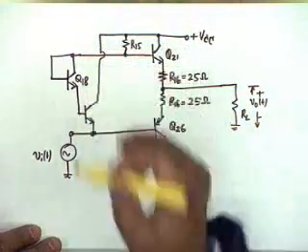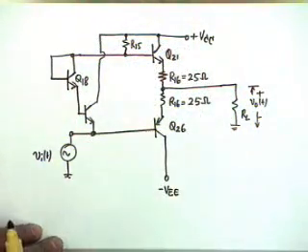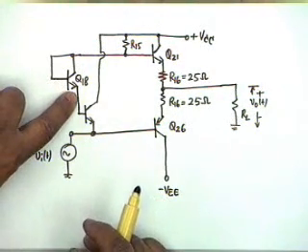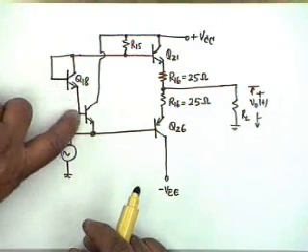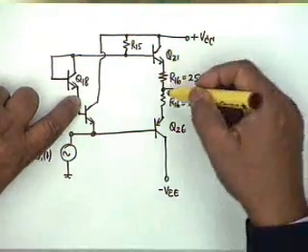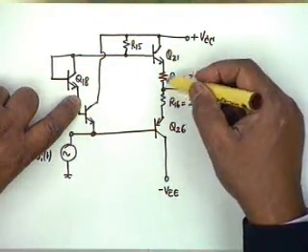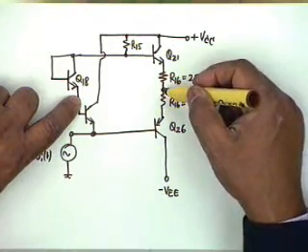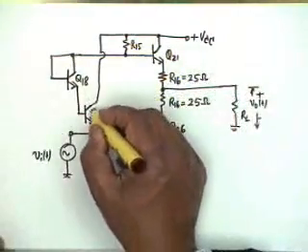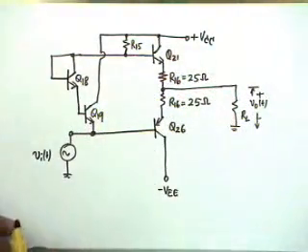Does this make a difference? As far as the balancing is concerned, this base to emitter shall be 0.7 and this base to emitter shall also be 0.7. All that we needed was that this junction should be the same potential as this junction, and from symmetry there is no reason why these two voltages should not be equal. Q18 and this is Q19 are identical transistors, and therefore the voltages at the base, VBE, should be identical.